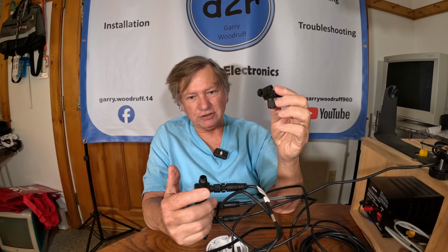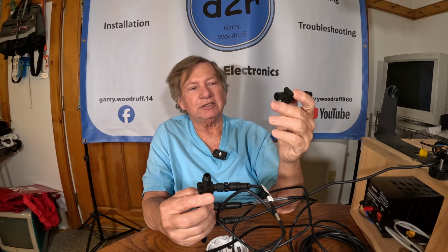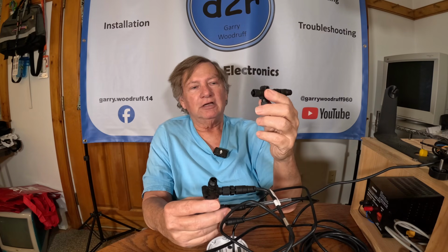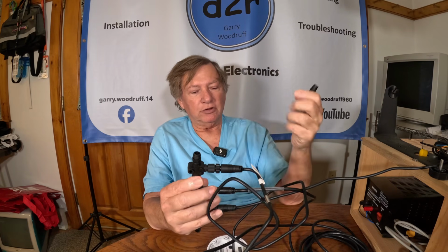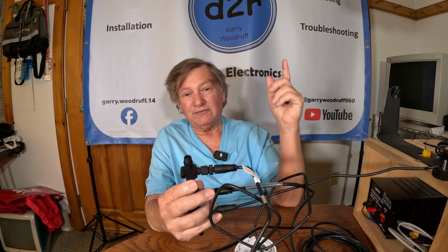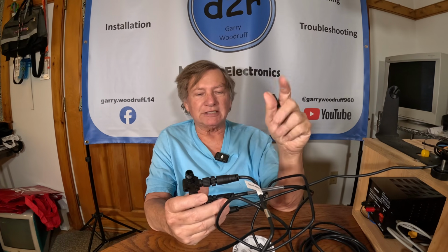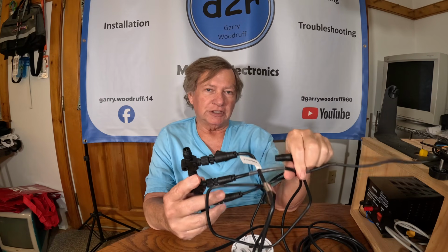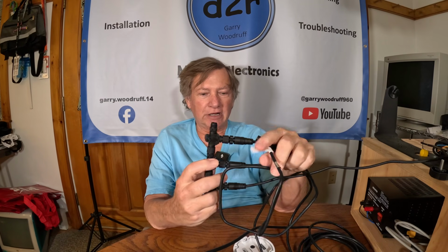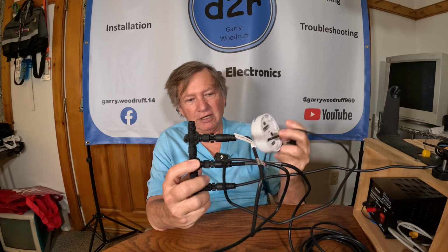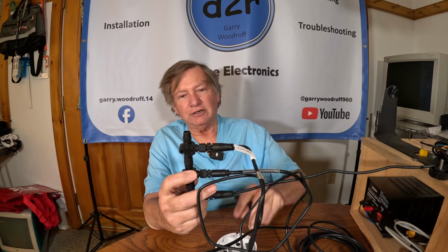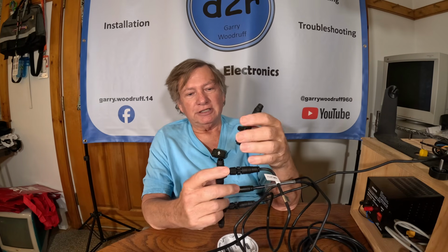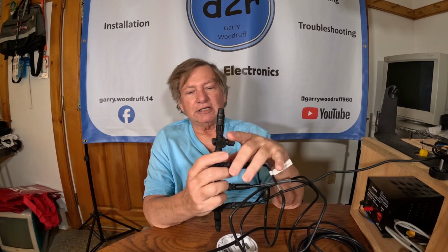There are limitations on the number of nodes you can have on NMEA buses. There's a power requirement that you've got to have. There are also limits on the drop cable length. 15 feet is kind of the max you want to do. Typically on my boat, I'll either have a 2-foot or 6-foot drop to the units, and I'll use whatever drop cable I need for, like, a Point-1. Usually that's near the NMEA connections as well. So that, in a nutshell, is what the NMEA bus is and how you connect it up.